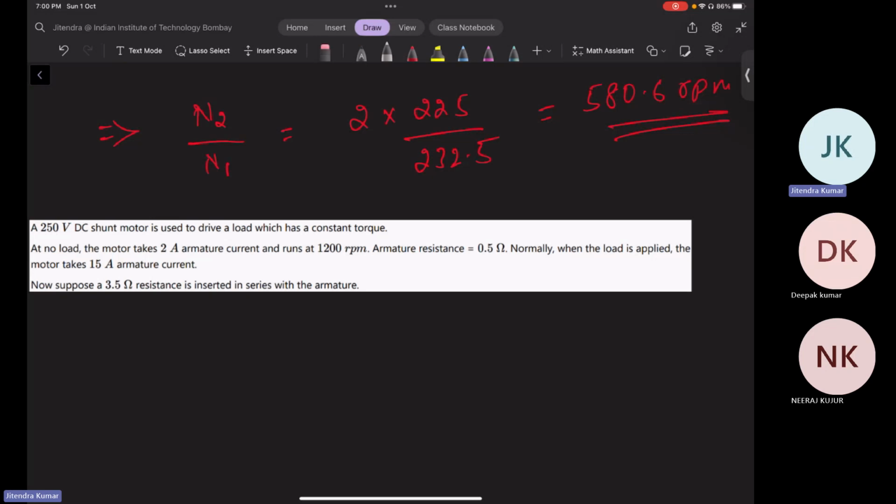On the field winding, you are exciting it with current, just the conventional one with brushes and commutators, just like a DC motor. And on the armature, you have armature winding. So you are not using permanent magnets. It is your conventional synchronous machine which you study in undergrad, which has been used for 200 years or more.